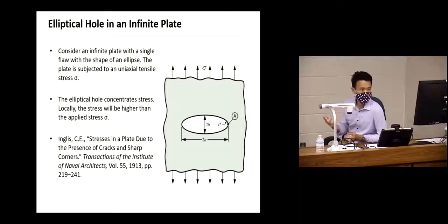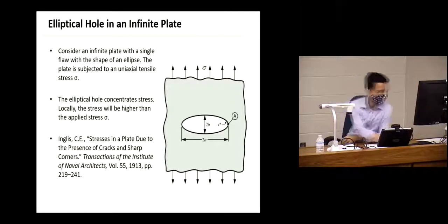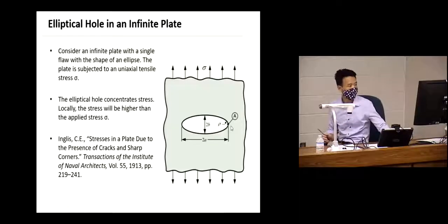Under this applied stress, we're going to see the maximum stress around point A, right? Just right at the tip of that elliptical hole, right? So this is where we expect the stress concentration to be appearing.